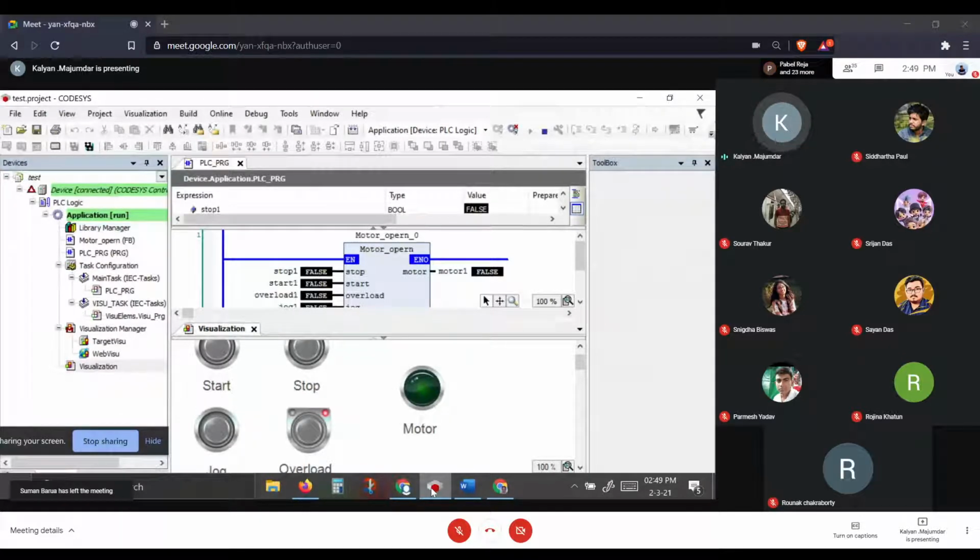If the current is above the rated value, pointing to an abnormal operating condition, then it becomes open, stops the operation of the motor to ensure safety. Of course, since we don't have a motor, we don't have a physical overload sensor. So the function of the overload sensor is being simulated by a switch that was manually operated. So if you press the switch on, that would simulate an overload condition. If you press the switch off, that will simulate a normal operating condition.